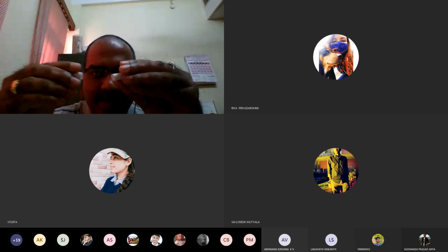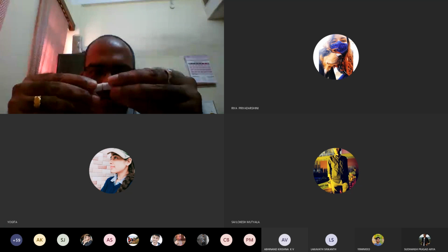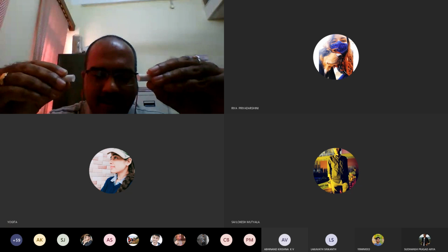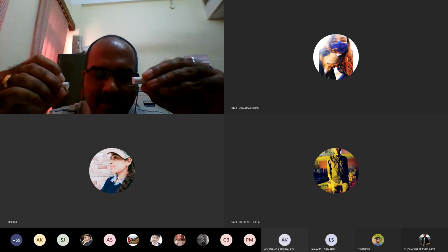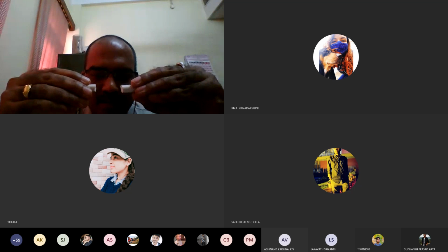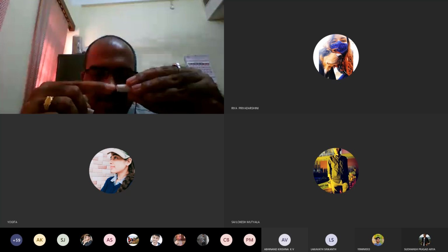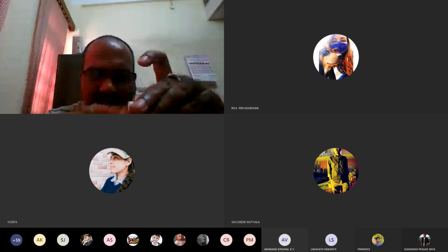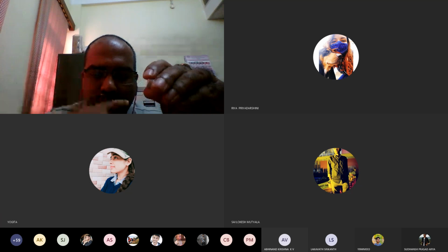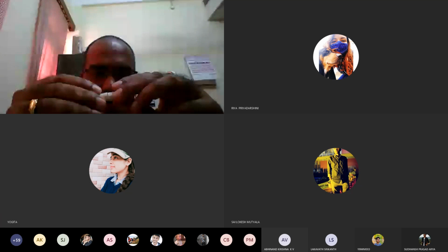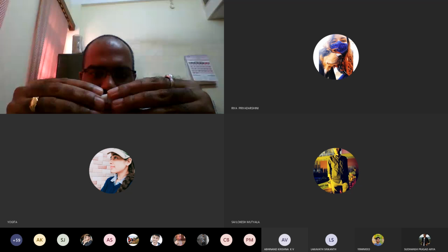This means that the stress value in this chalk piece is sigma x, and the tensile strength is being reached. So the tensile strength is equal to the applied stress. The shear stress in the chalk piece is sigma x by 2. That is, the maximum shear stress is sigma x by 2, which is acting at some 45-degree angle. But the shear strength is greater than sigma x by 2. So this is regarding this chalk piece.